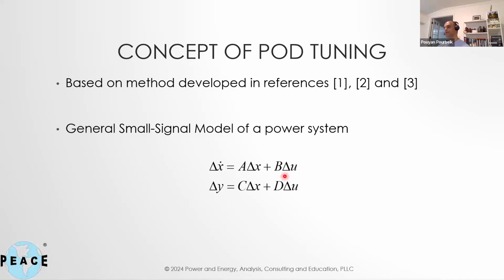The inputs would be all the reference inputs that are coming into all our controllers, our IBRs, our voltage regulators on synchronous machines, our governors on synchronous machines, etc. Or our inputs to our power oscillation dampers, so on. And then outputs would be, well, what we see out on the network. Electrical power coming out of each generator, reactive power coming out of each generator, power flows on lines, frequency of the network, these things. These would be our outputs.